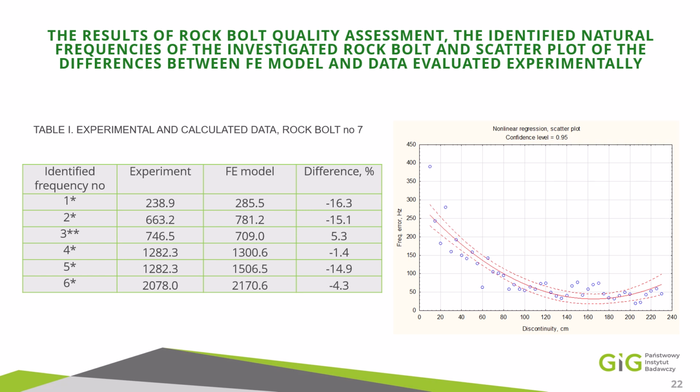And much effort should be taken to control these phases, especially the turning and spinning ones. Otherwise, the grouting connection may not occur. Too rapid insertion of the rock bolt may lead to leakage of grout from the hole, and lack of grout in the back part, close to the end of the borehole.